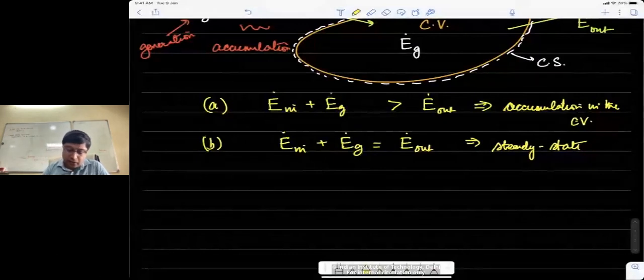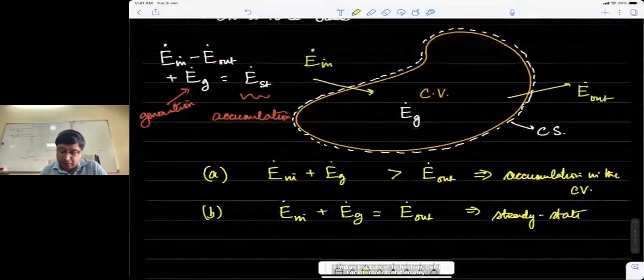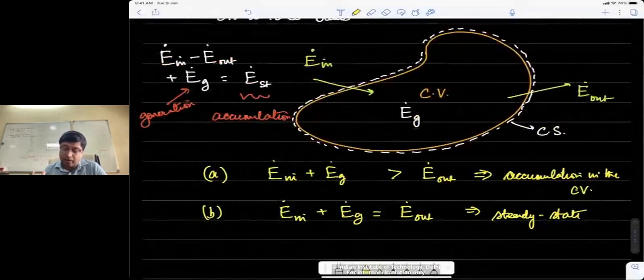The other thing that you should now remember, and you've done this in fluid mechanics, by the way, but I should reiterate, is that exchange of matter or energy happens, as I said, across a control surface. So it is what we call a surface phenomenon. But the generation and storage terms are essentially associated with volumetric descriptions. So generation and storage will actually be volumetric phenomena.